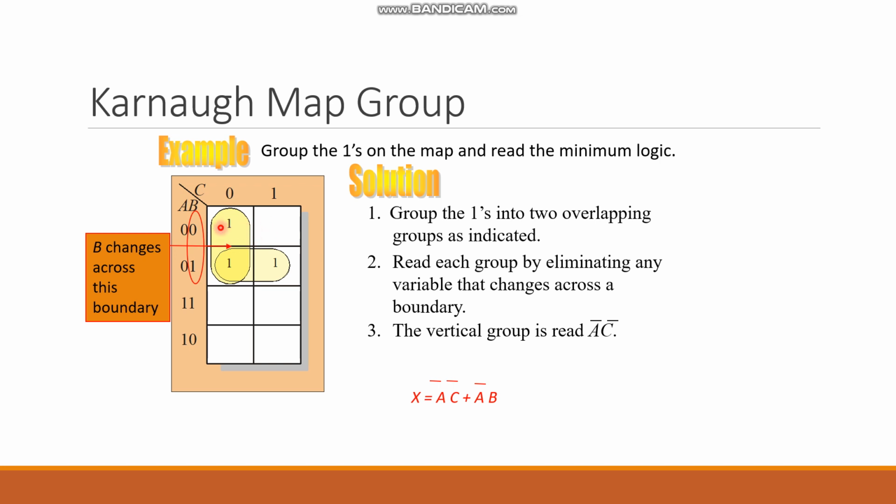So in this Karnaugh map, we have those 2 which are adjacent to each other. Look, we can't take those 2 ones directly together, because they are diagonally adjacent, which we don't take into account. So we can take those 2 together, and this one is going to be remaining alone. So when it's alone, we look for its adjacents. Are there any other one? Yes.